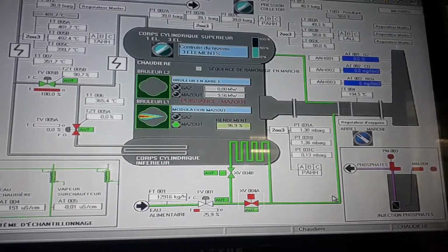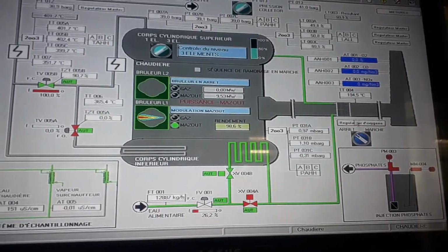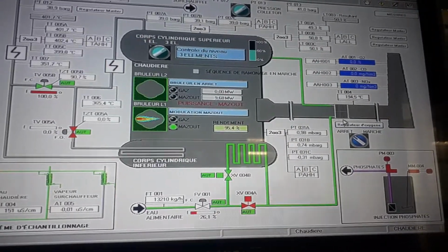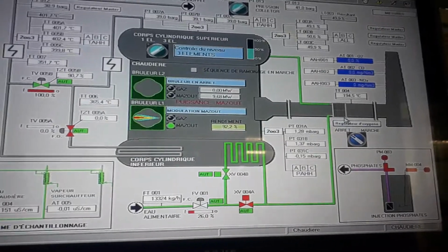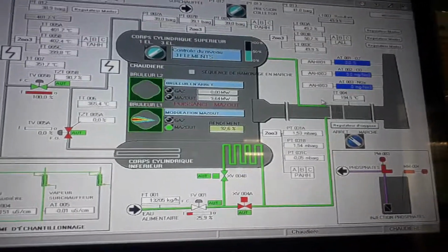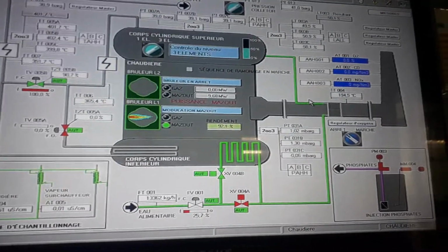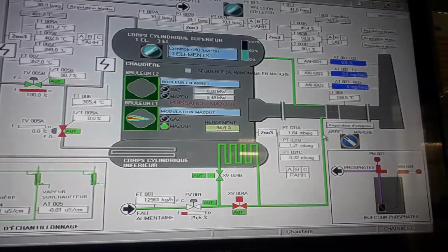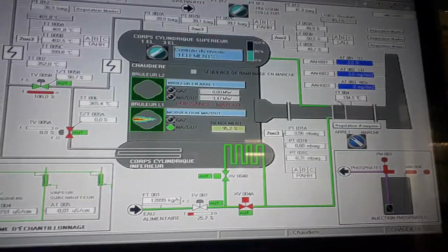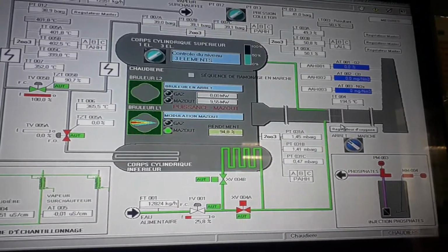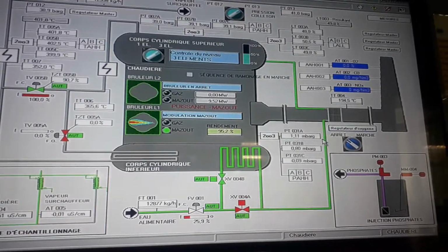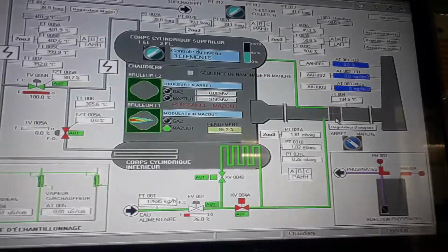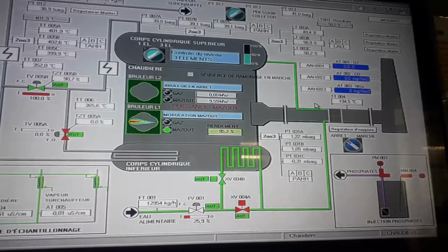After the preheater, the water goes to an economizer, which is a tubular heat exchanger between the water and the flue gases. The flue gases are given by the combustion of the fuel oil and the fuel gas in the combustion chamber. The water enters this economizer at a temperature of 130 and a pressure of 42 bar. The water enters the tube side to reach a temperature of 230.